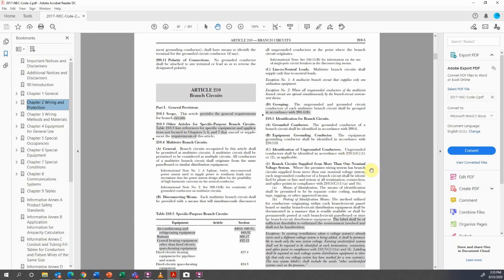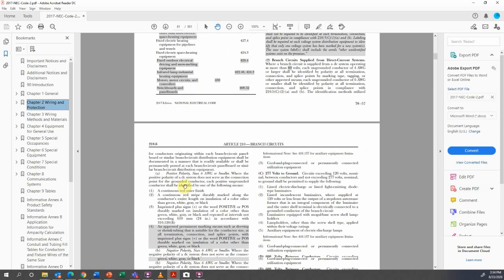So you go down into the details of the specifications in the National Electric Code, and sometimes these layers go pretty deep. So 210.5.C.1a involves the means of identification, shall be permitted to be by separate color coding, gets pretty specific as well.